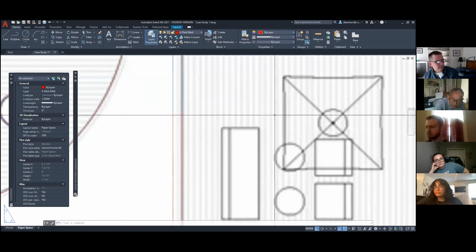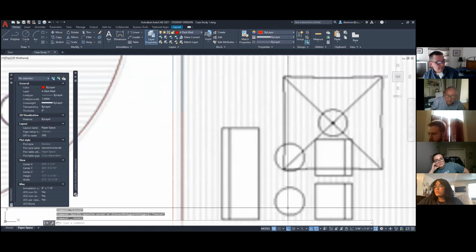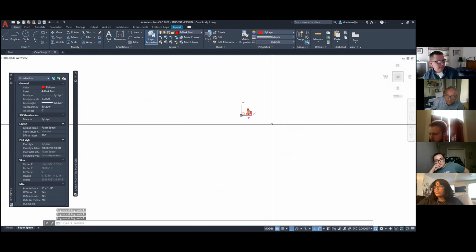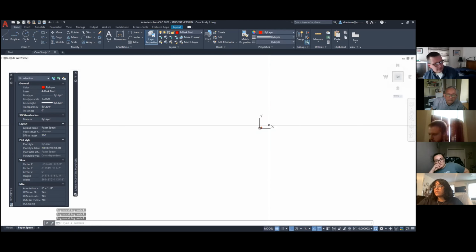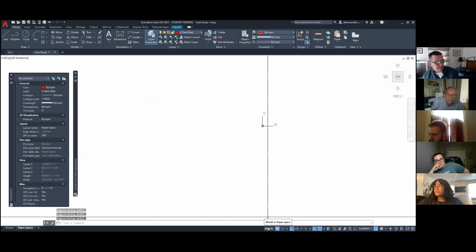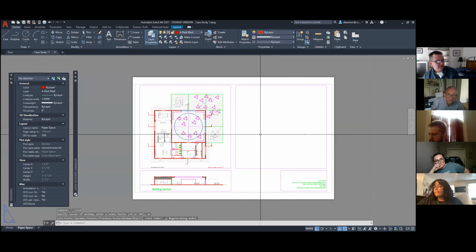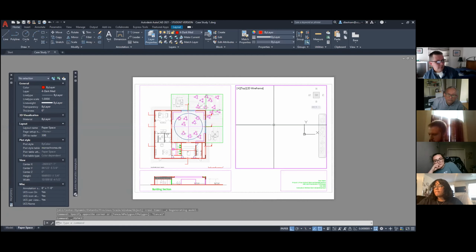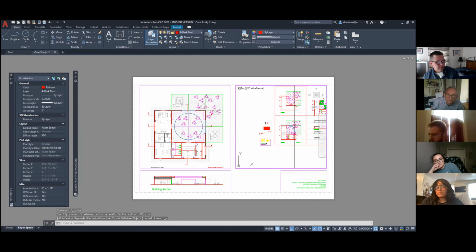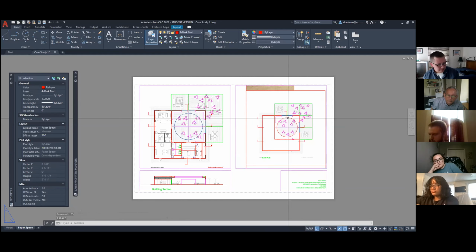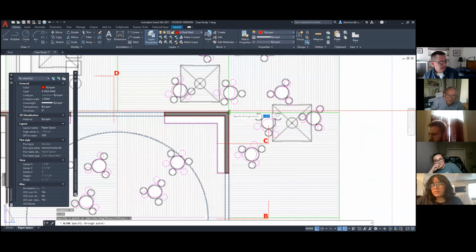So if I come in, double click, now I can't see. Now I'm unaware that I'm in model space, unless I'm paying attention to that. But it was a mistake, you know? So I'm looking through the window into model space and said, uh-oh, messed it up. Now I'm in paper space, double click, zoom extents, lost my plan, double click the wheel, and there it is.